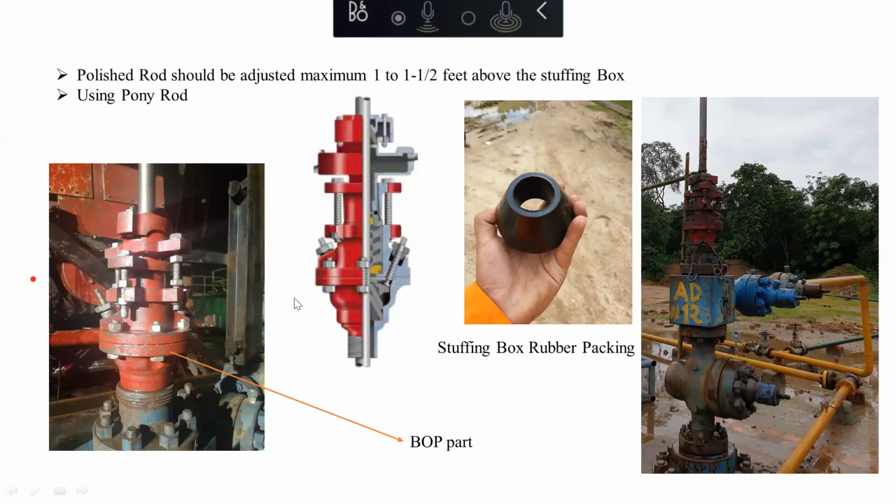That is, you are injecting water using pump through your tubing. After you install your sucker rod as well as your polish rod and your stuffing box, you are going to test it using your polish rod. You are going to give a reciprocation motion in your rig, and if the pressure holds, your pump is okay.